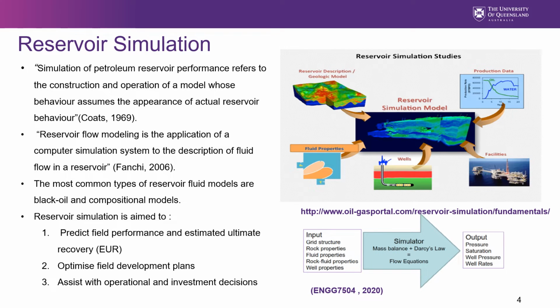In addition, reservoir flow modeling is the most sophisticated methodology available for achieving the primary reservoir management objective for a hydrocarbon reservoir, which is to determine the optimum conditions needed to maximize the economic recovery of hydrocarbons from the operated field. In this case, we will explore how reservoir simulation can be used to predict coal seam gas well performance.